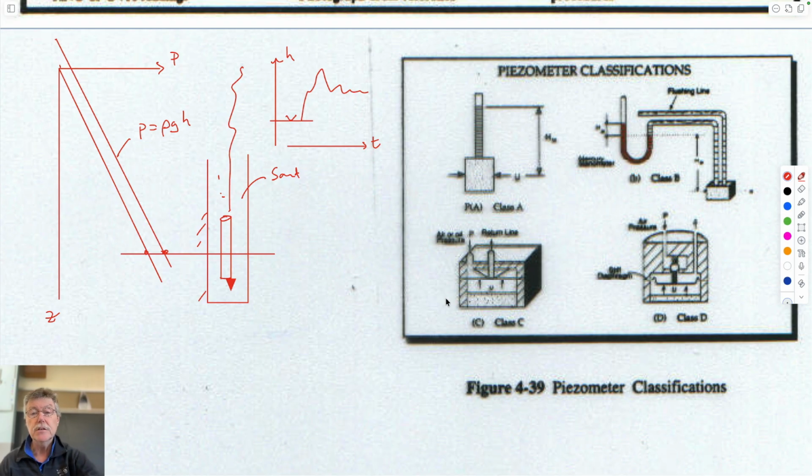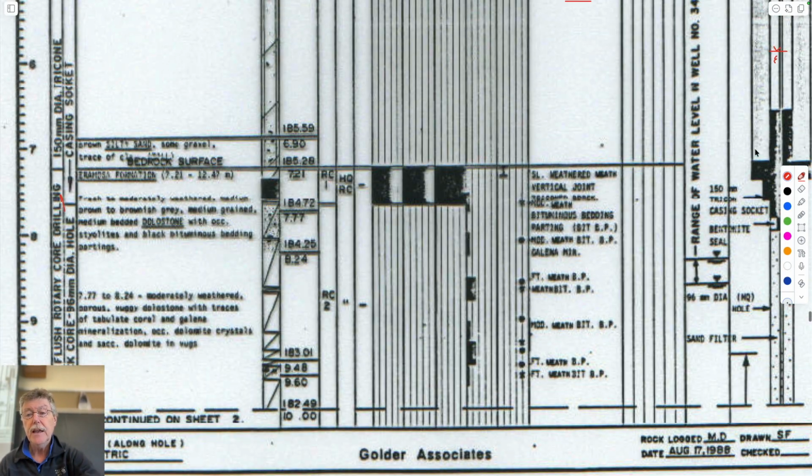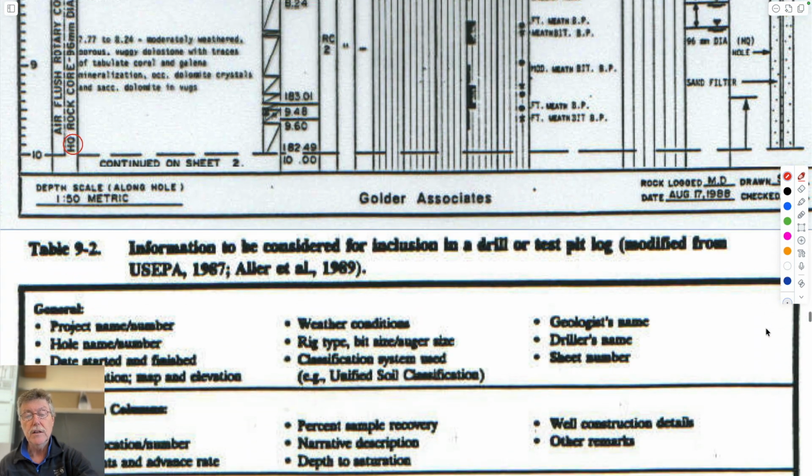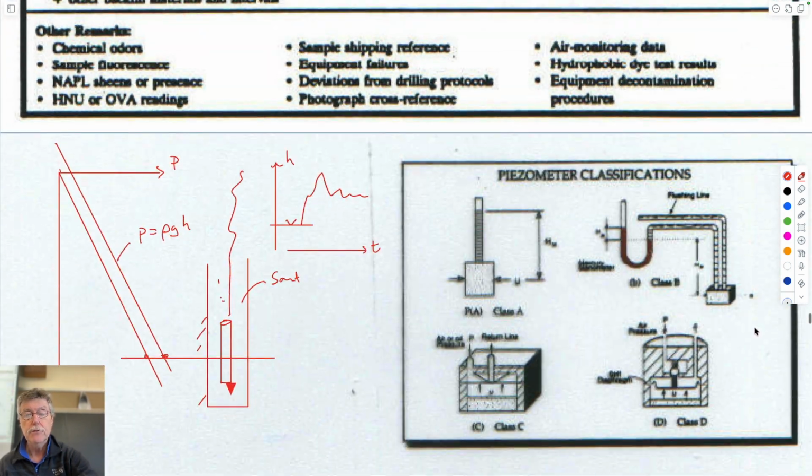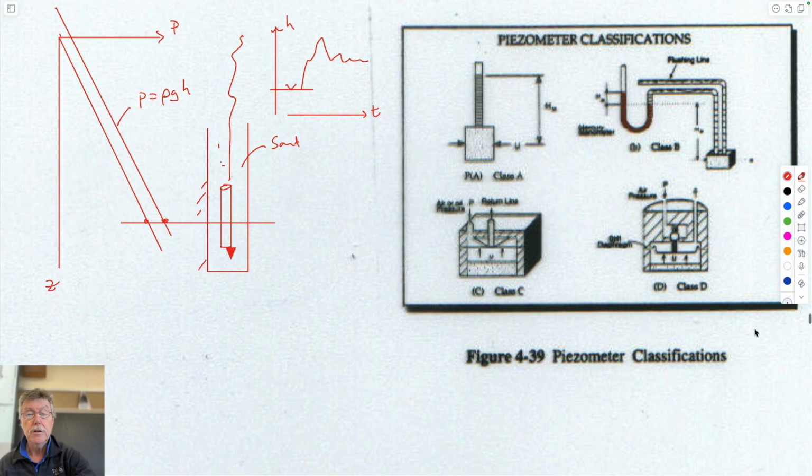Standpipe piezometers that we just talked about allow you to sample, even though it's an inch diameter pipe, inner diameter, you can still get liquid samples out of that, which will represent whatever the plume might be contributing. So different forms of piezometers.